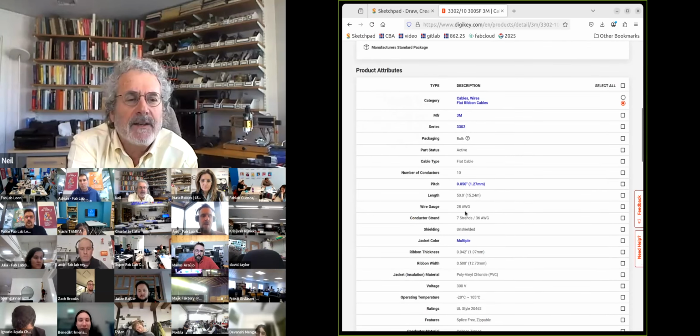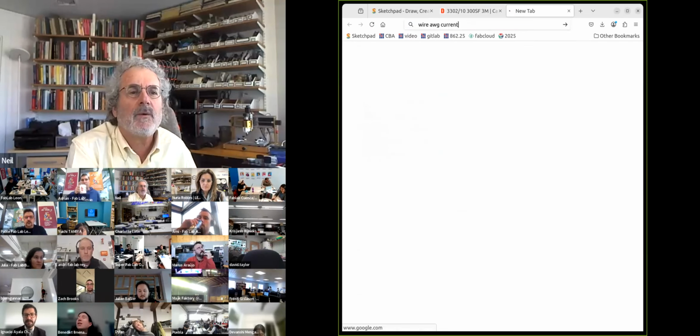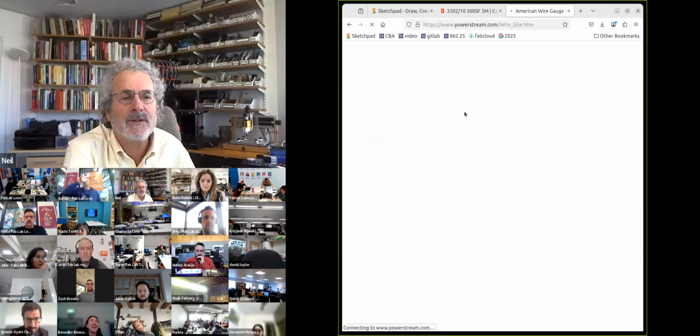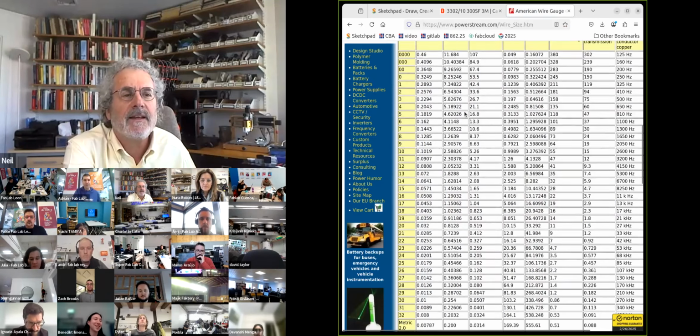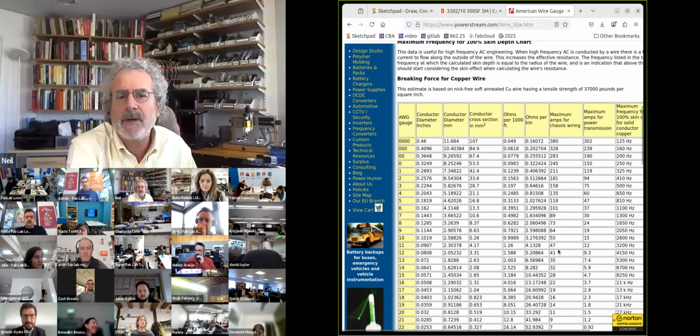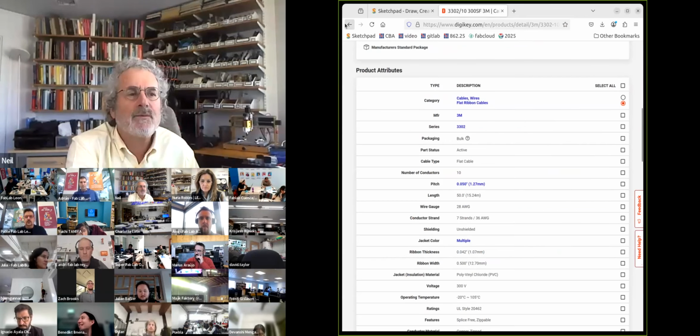Wire is specified by AWG, and so that's 28 AWG. And if you search for wire AWG versus current, you'll find all sorts of versions of tables that tell you the wire gauge versus the current that you can handle. So more current needs a fatter wire. So that's what we use for hookup.